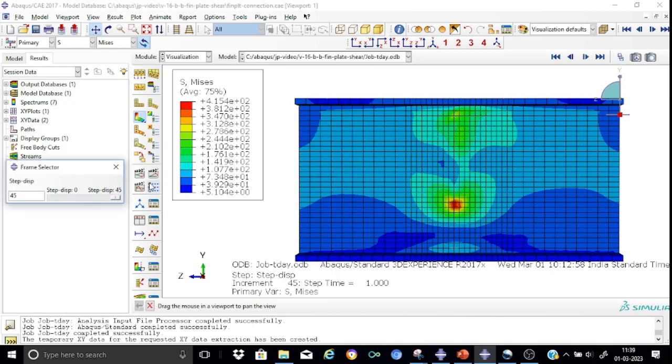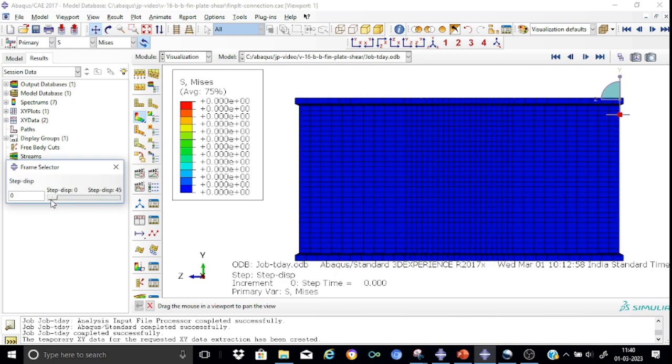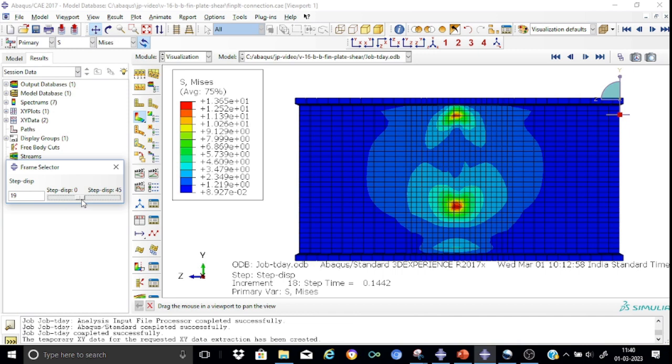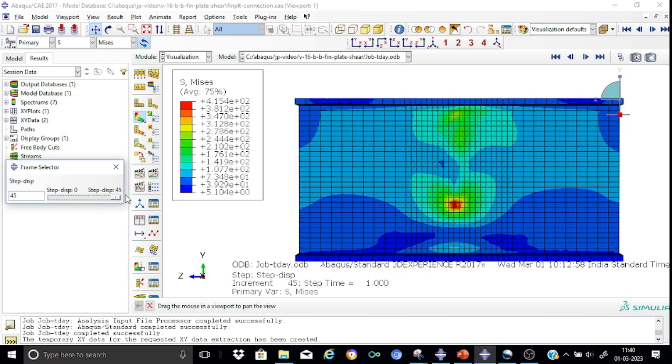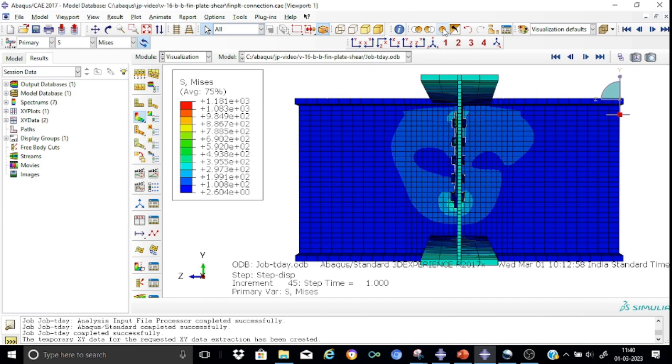And if you want to see how the stresses varied, you can see that's how the stress distribution looks over the members or the main beam. As expected, we find that the stresses are getting constrained in this middle portion. We don't have much problem. So now let us see the other component, that is, let us investigate the secondary beam.